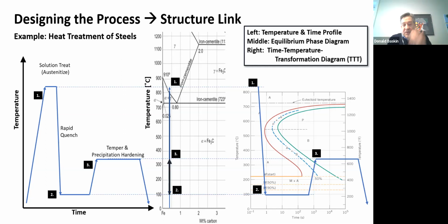of this martensitic steel. And you use an intermediate heat treatment called tempering, where you form what's called tempered martensite. And to a large extent, there's some other phases that are precipitating there. The little martensite needles are getting a little bit bigger. They're coarsening, they call that, with the temperature and time, which can increase the toughness of the material, sometimes substantially, but it increases the strength of the material, or the toughness of the material, which is important. You can have too much strength and end up with too little toughness and be in trouble.